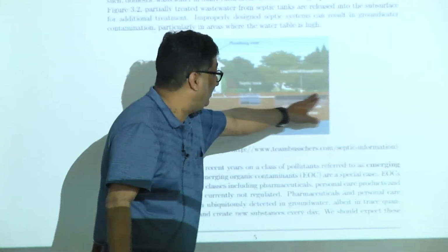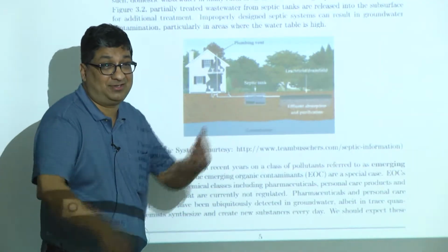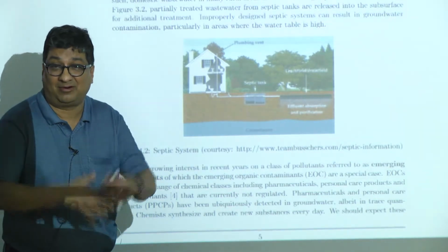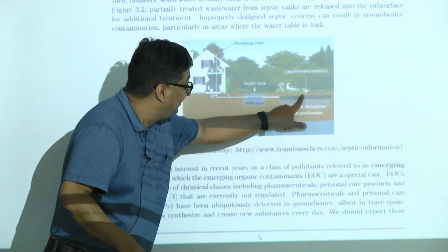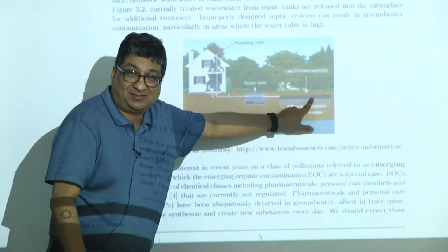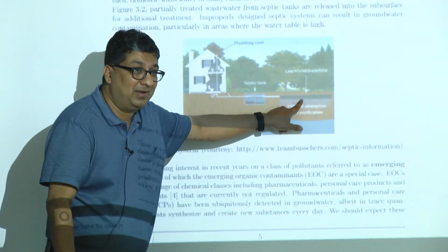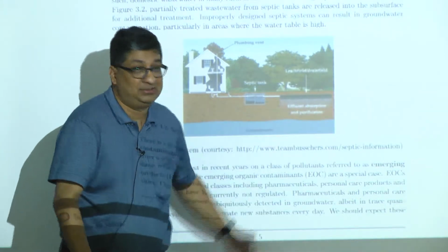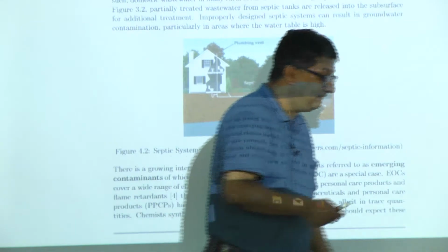So this is all aerobic, right? So we have ammonia here, or nitrogen is NBOD, mostly ammonium, the reduced form, or organic nitrogen, right? It comes out, leaches. So we are oxidizing that nitrogen compound, which means we form nitrates. So by the time the water gets into groundwater, we have added nitrates. Good or bad? Why?